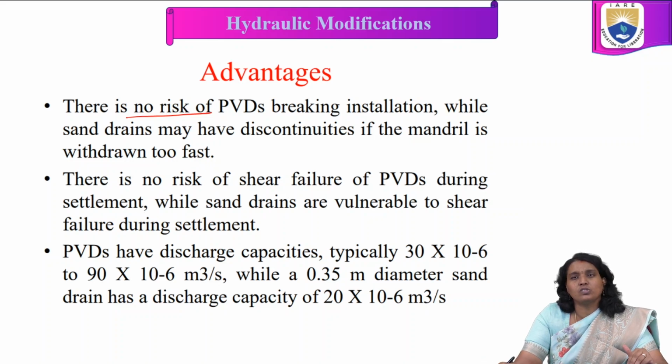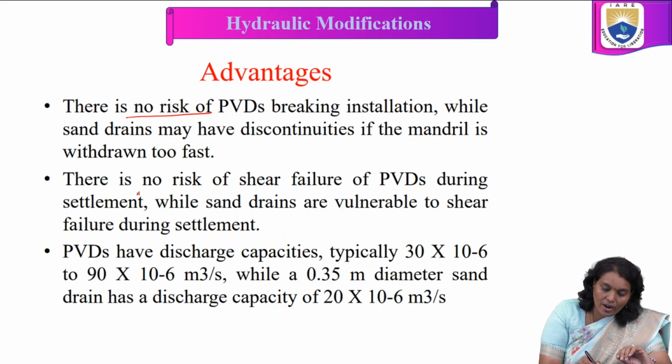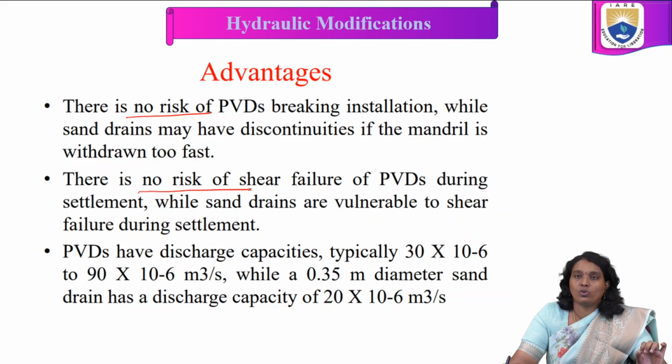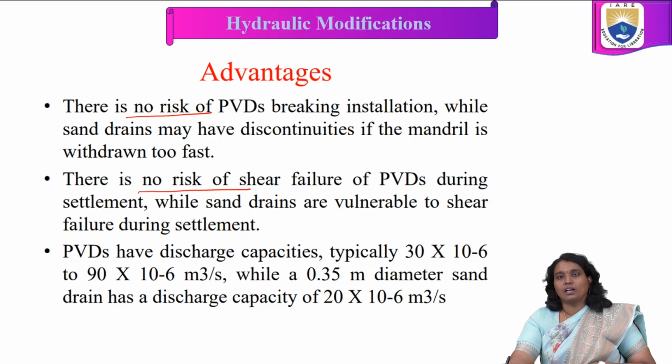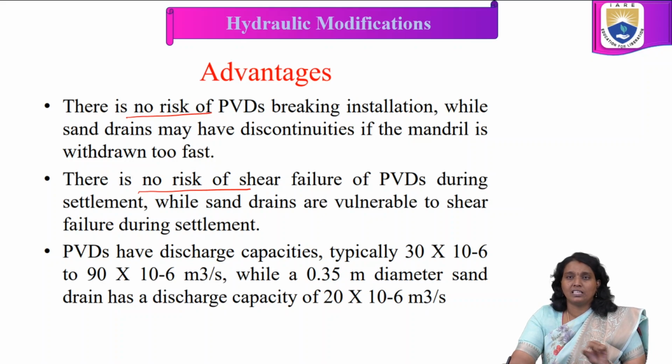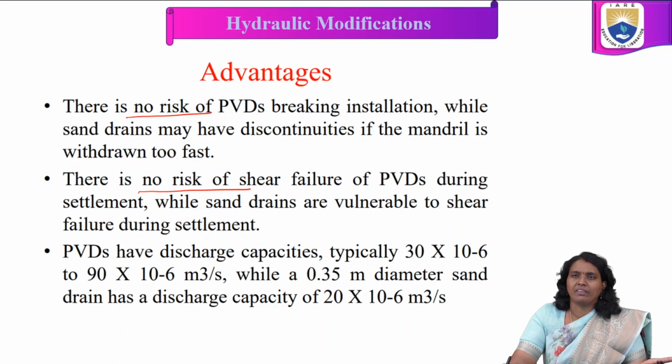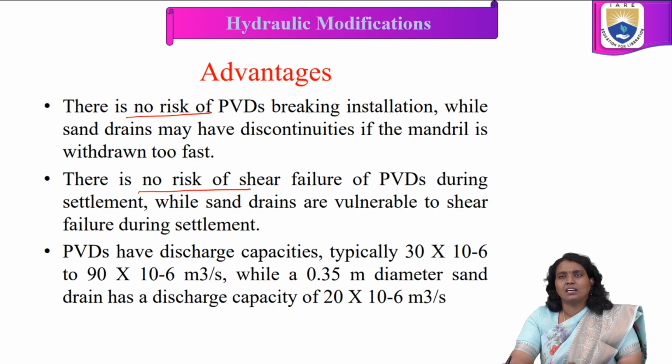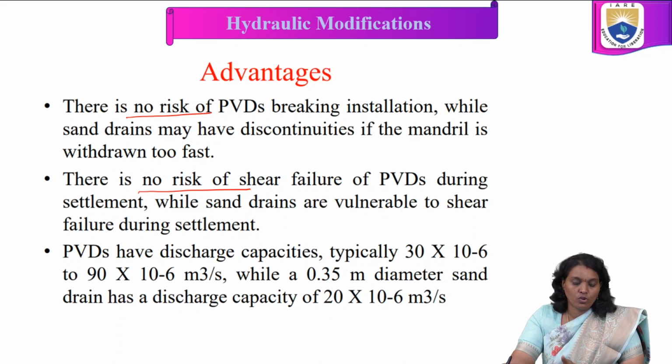Coming to the next point, there is no risk of shear failure of PVDs during settlement. At the time of settlement there is no risk from the shear failure point of view, while sand drains, as we already observed in the previous lecture, are vulnerable to shear failure during settlement. And next, PVDs have discharge capacities typically